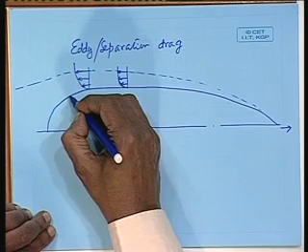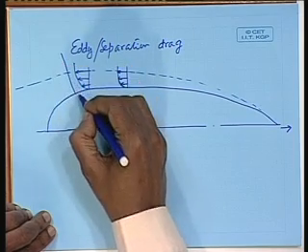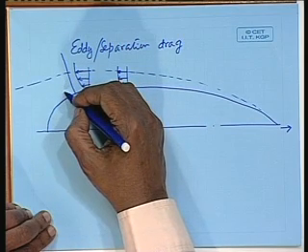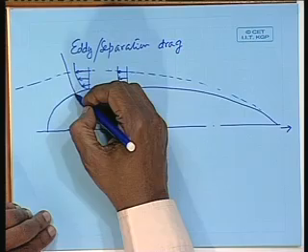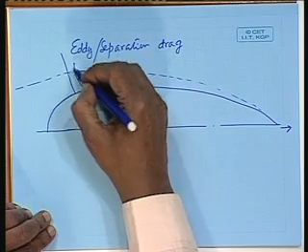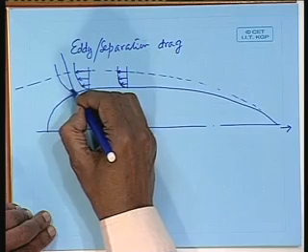Now, it has started sloping. So, what will happen here? If I draw a velocity profile perpendicular to the ship hull, there is an increase in pressure. Therefore, decrease in velocity, and that will affect the point near the body. So, instead of going like this, it will start going like this, where this velocity is reduced.